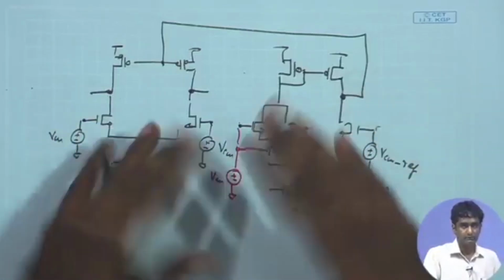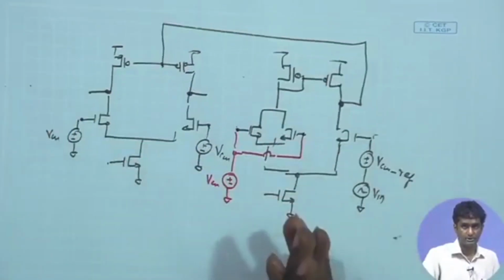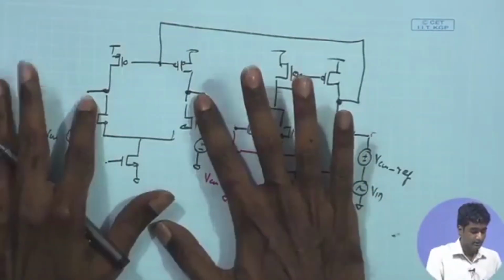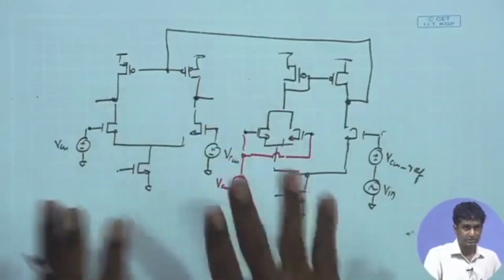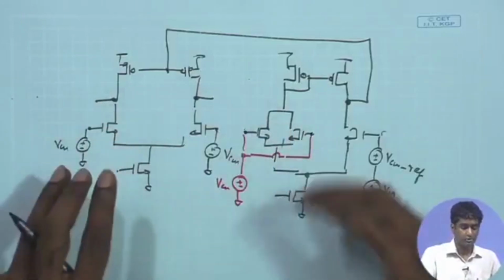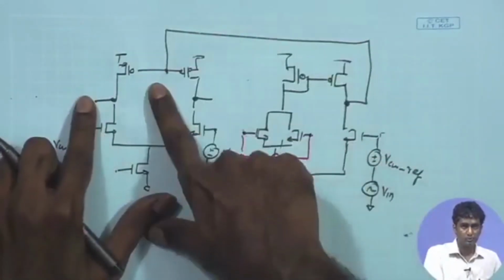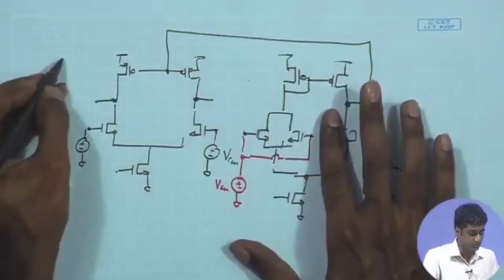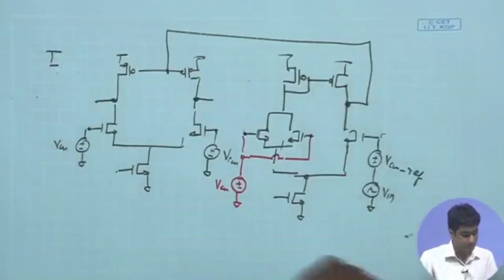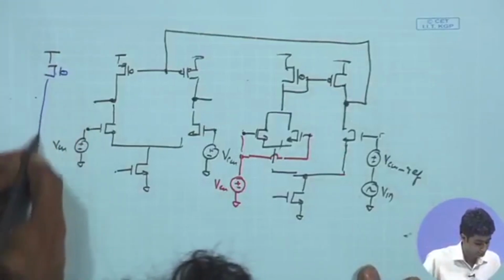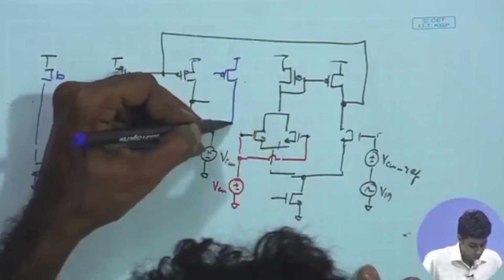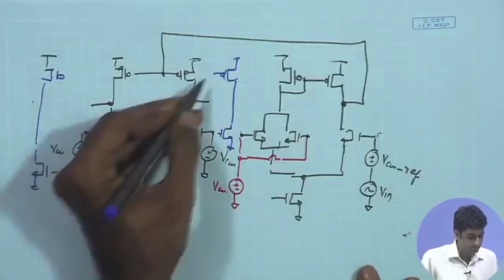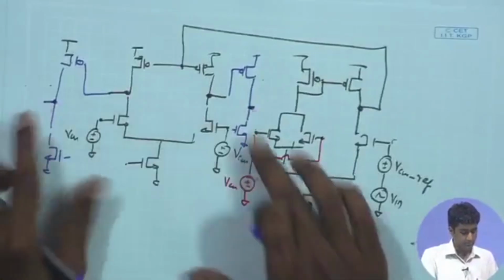Likewise, if we do the common mode feedback for the whole two stage, there also similar biasing conditions need to be checked, and ensure that the overall error amplifier and the two stages are maintaining the same biasing scheme. And suppose you are using the same single loop for the common mode feedback, then overall the scheme remains the same. Only thing is, after that you will have another two stages added, which are the common source stages, so these are the additional stages which get added, and your output, you are taking it from these 2 points.